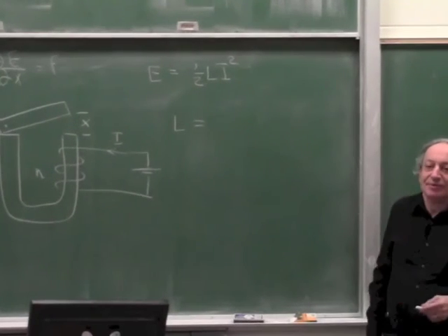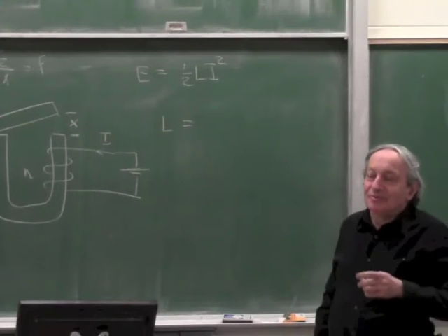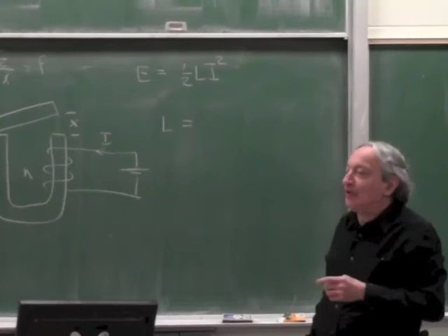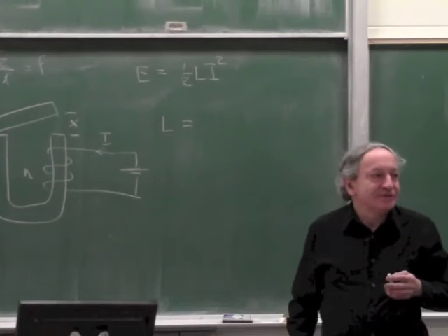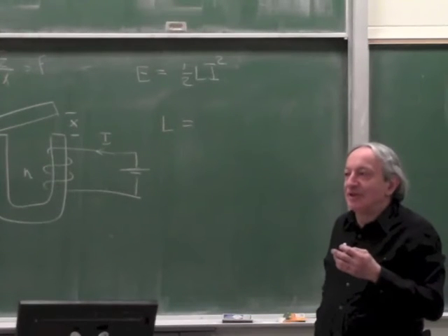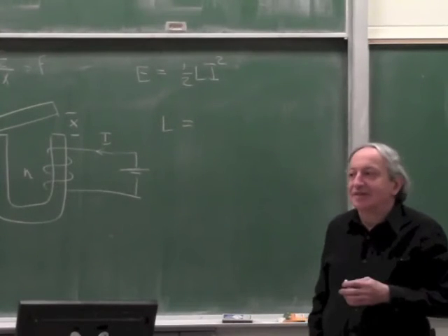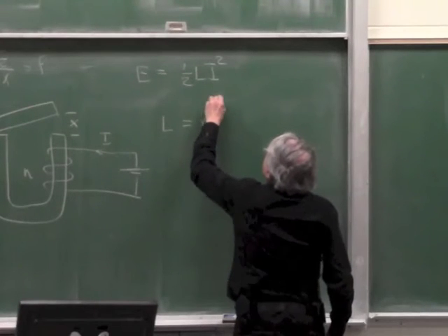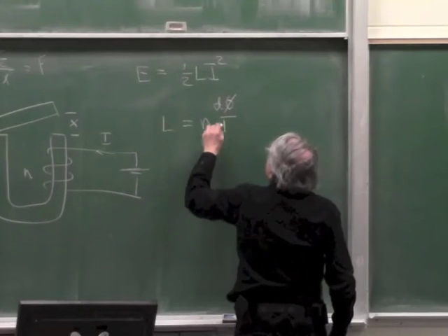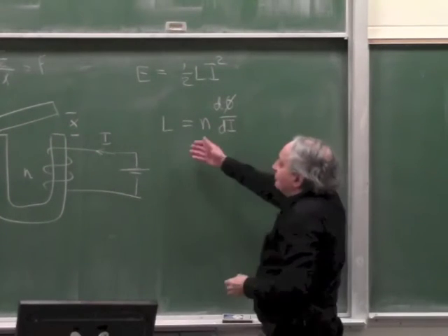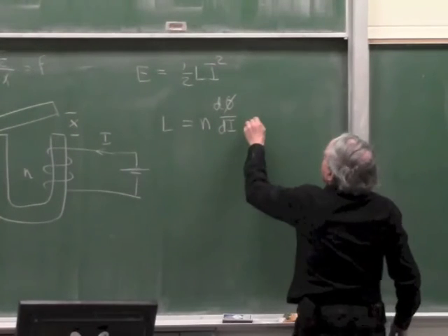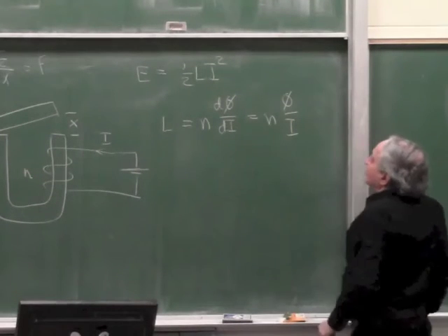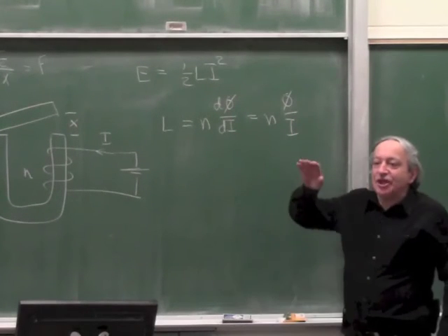That's a bit harder, because some of you never learned that. Does somebody know the formula for L for an inductor? It's actually a definition, not a formula. The definition of inductance is N delta phi over delta I, and if it's linear, since most inductors are linear, it is N phi over I. It's only delta phi over delta I if the inductance changes with current.